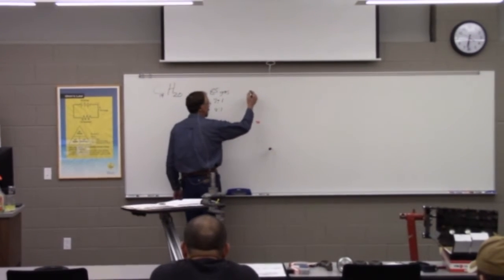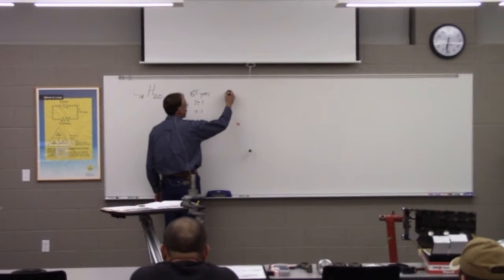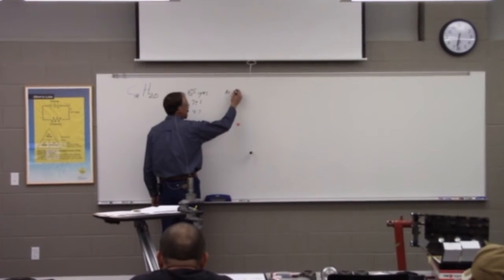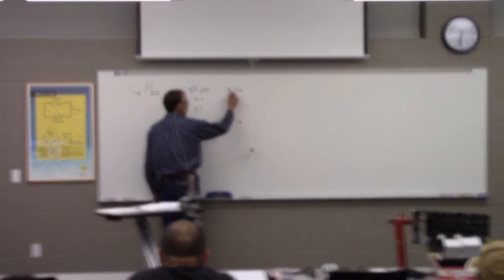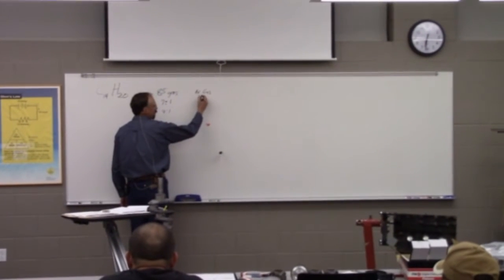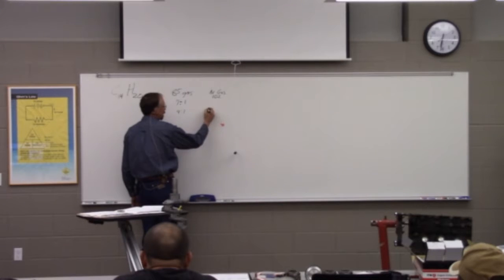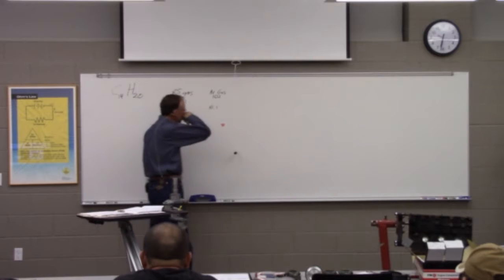And I want to talk about those compression ratios, but what we would call avgas, aviation gasoline, which is typically somewhere in that just over 100, we'll just say 102 octane, will run at those ratios, but it can run up to 10 to 1 real well.